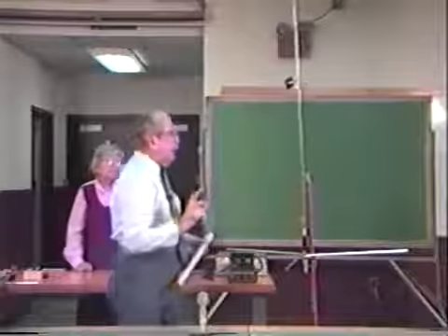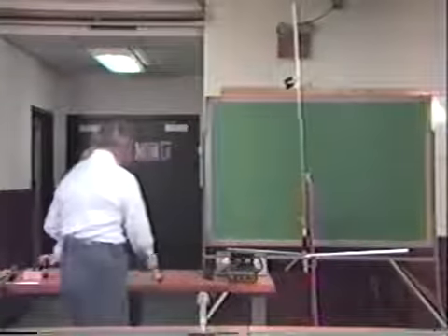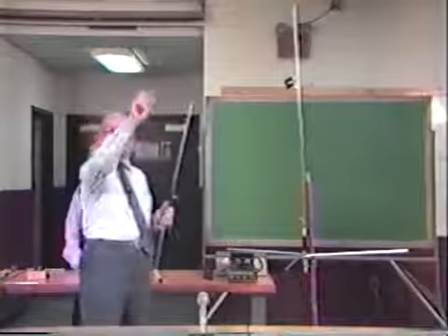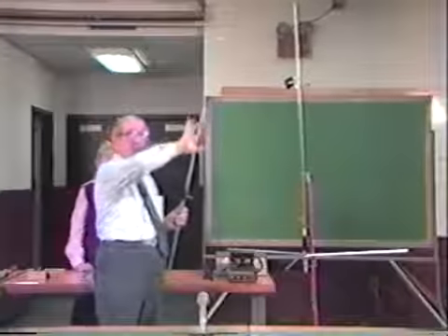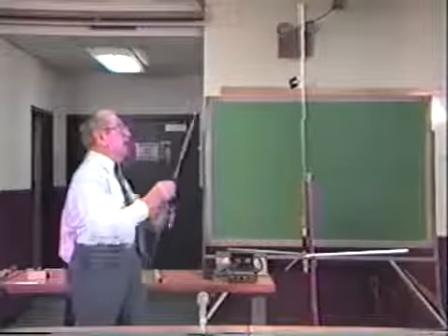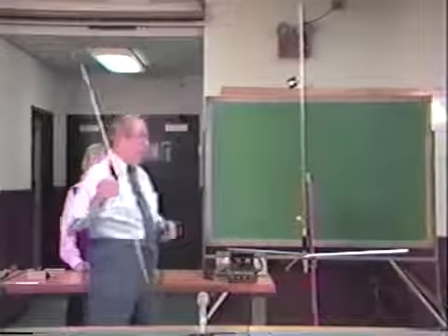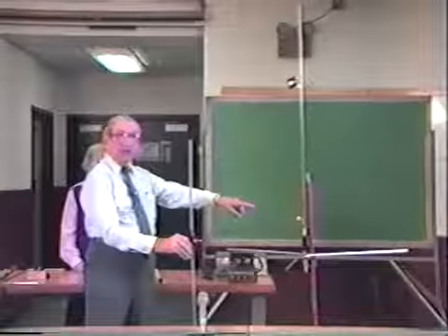Now, as I pointed out before, the radiation characteristics are such that the current loop is the portion that's sending out the radio waves. So at this point here, we'd have our radiation, and we'll also have radiation from the electrical field that's developed in this portion of the antenna.